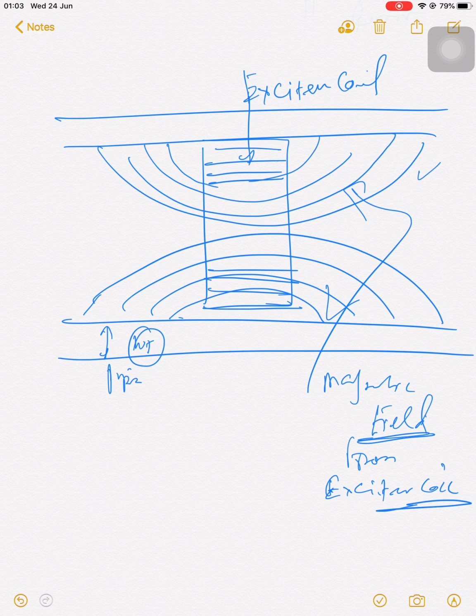This eddy current creates another magnetic field of its own. The exciter field is dominant, but the eddy current field extends more in the tube. The magnetic field lines of the eddy current are cut by the moving receiving coil, and this produces an electromagnetic force in the receiving coil. Monitoring the voltage induced in the receiving coil can help in finding the direction of flow in the specimen.